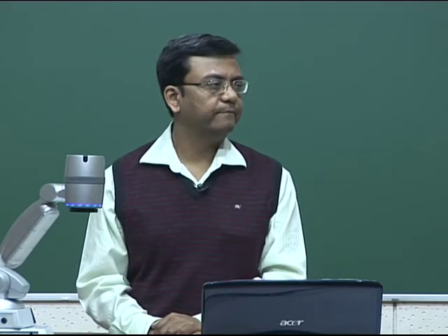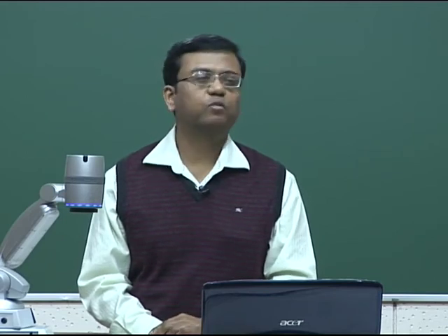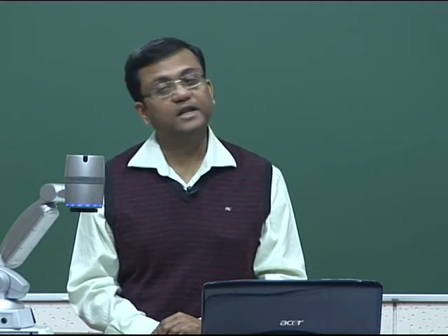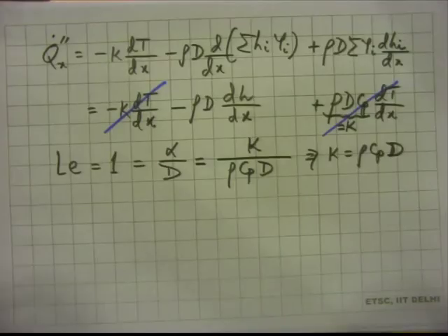Now, can this be justified to some extent? Yes, because Lewis number in typical combustion situations are of the order of 1. By of the order of 1 I mean maybe 0.7, maybe 1.2, things like that, but not very far away from 1. So, if you take a realistic mixture, calculate alpha and d and then take the ratio alpha by d to calculate the Lewis number, it is of the order of 1. So, we are not very far off from 1. It is not equal to 1 definitely. You have to be extremely lucky to get a Lewis number equal to 1, but it is of the order of 1, and in many theoretical analysis of combustion you assume Lewis number to be equal to 1 for the sake of simplicity. It so happens that taking Lewis number equal to 1 will still give us something reasonable.